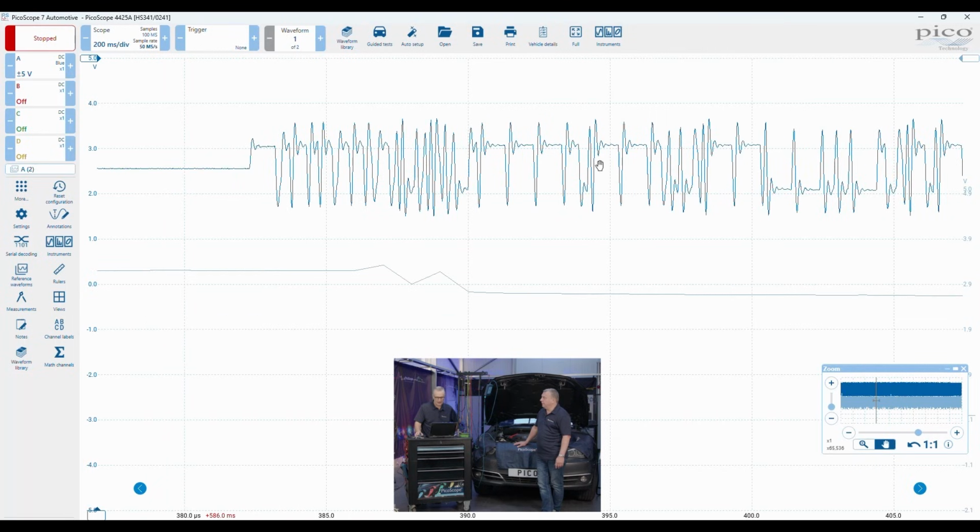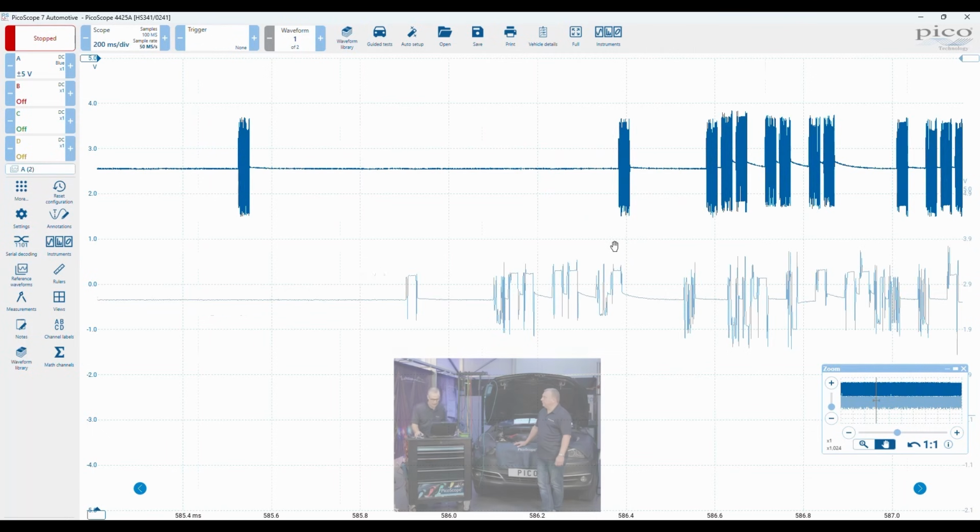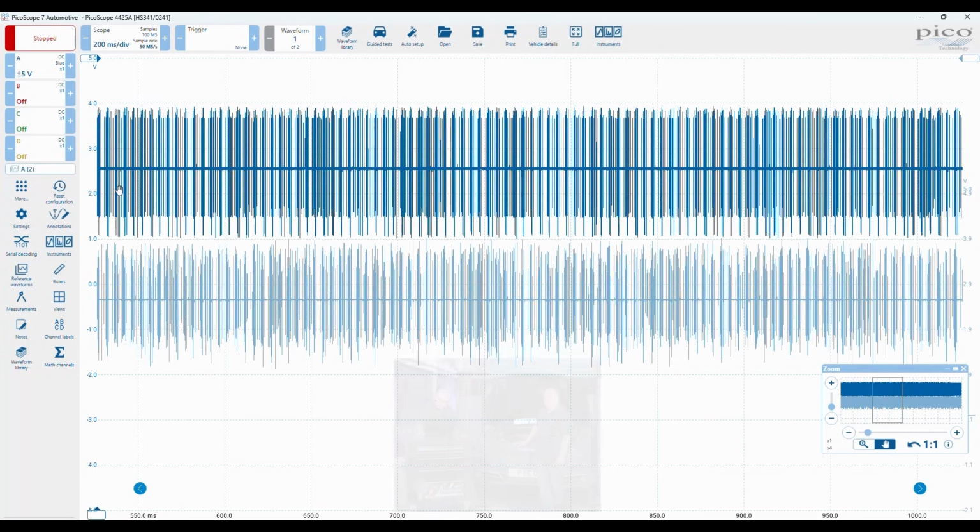Overshoot. And we discussed this before. It's quite common. The system can tolerate that, but is that now the system, or is it our probe? Are we influencing the signal? We'll take another reference waveform, and we'll keep that one on, because we know that that one is 50 million samples a second. And then we'll move on to adding another probe and see what the effects are there.